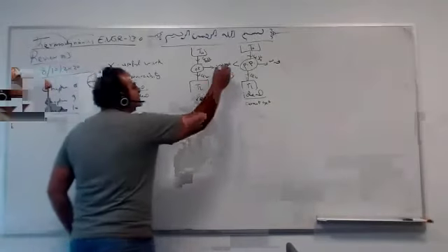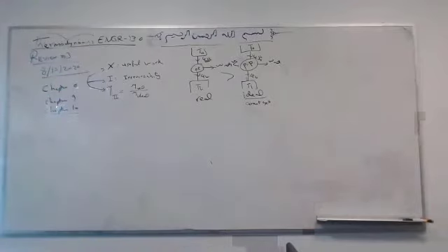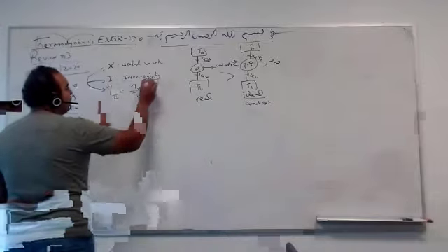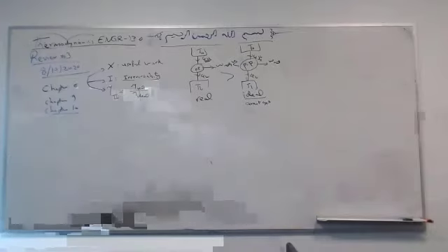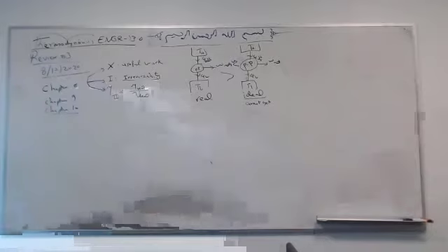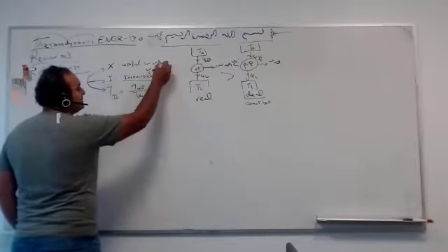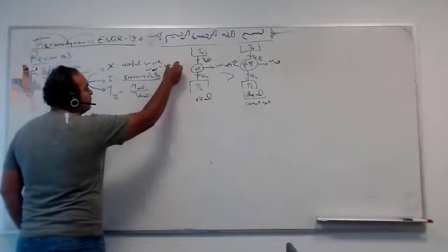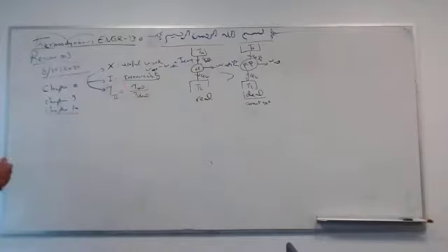This we call useful work. We wish it to be larger. Irreversibility is the difference between the maximum you can get minus the minimum. Like, for example, a compressor: W actual minus W ideal. W actual is bigger because we need to pay more for a compressor. This is I compressor. The same for a turbine, but opposite.